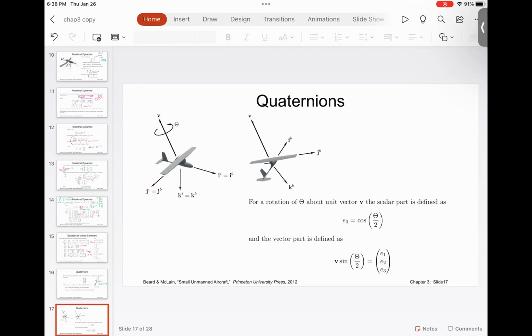That is the beauty of the quaternion. If you want to propagate a direction cosine matrix, you have to keep track of 9 elements. But if you propagate quaternions, you just have to keep track of 4 elements. That may not seem like a big saving, but when you are performing the flight calculations 1,000 times a second, every calculation saves a lot of time. Over time, quaternion multiplication is more efficient.